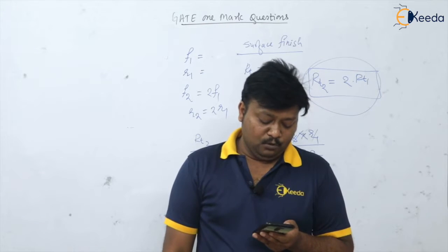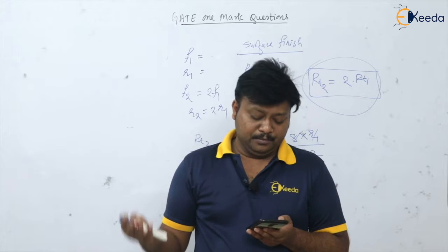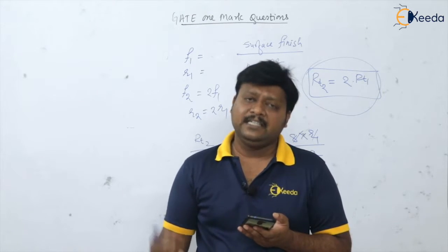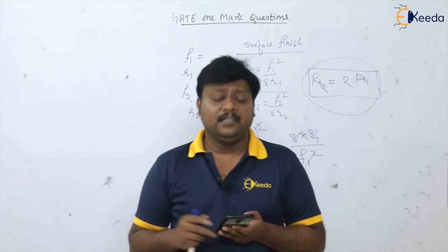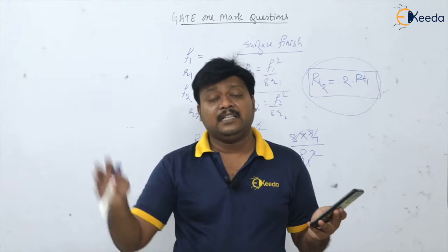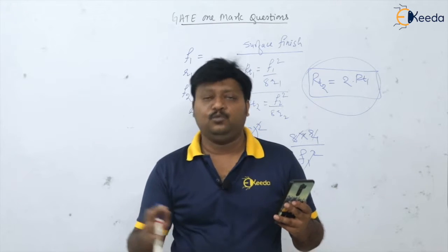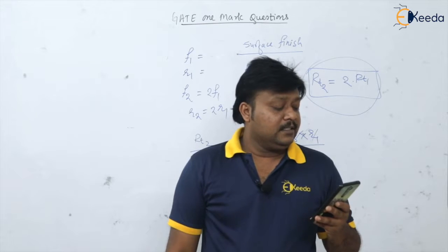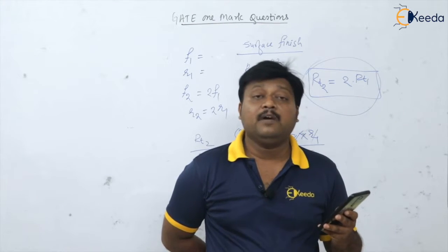Next, the most of the metal cutting heat goes into chip, cutting tool, work material, machine tool. We know that maximum heat is carried away by the chip only. Around 75 to 80% of the heat generated is carried away by the chip. So who carries more heat: first chip, after that work and the least is tool. We know the sequence. Next, cutting power consumption in turning can be significantly reduced by.